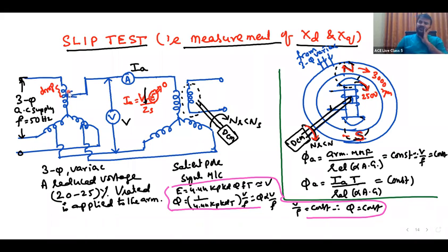For example, you kept 100 volts, it may be 95 or 105. That much only variation. In the laboratory, you can see the readings. For example, it is 90 volts, it may be some 100 volts. That much only variation. Got it, sir. Only a drop, not much variation. That's the reason I am taking voltmeter reading as almost constant. I told voltage constant, but later during the experiment that voltage also has slight variation. Why? Because current is varying, then drop is varying. Yes, sir. Got it, sir.